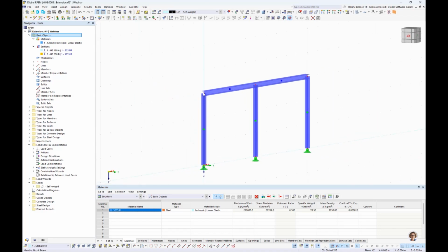We would like to enter it here in that area. So, you could enter it at the same height as the column height, with an eccentricity, and use line releases or line hinges. Yeah, that's still possible, but I would like to use a new feature, and that's also very good. That's the rigid link.